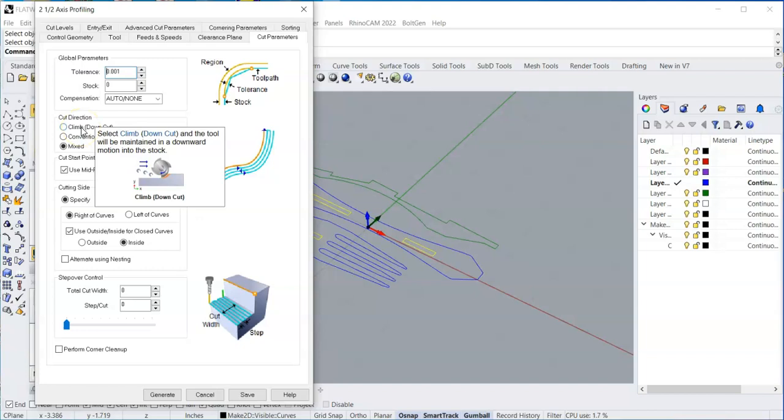It shows the end mill, and the flutes are basically the rotation of the cutter is going one way, but the cutter is always, or the table is always driving the work into the piece where it's climbing along. Now this climb milling gives you a little bit better finish. You typically use climb milling with harder materials. It's going to give you a better finish. It doesn't want to dig in, okay? Because you notice that the flutes are like throwing the chip out the back side, okay?